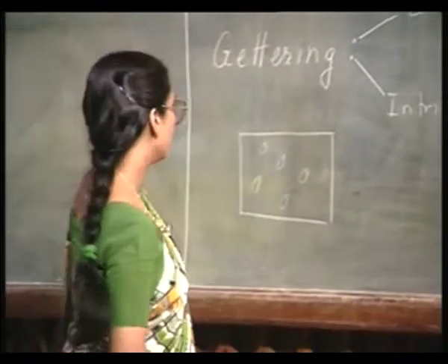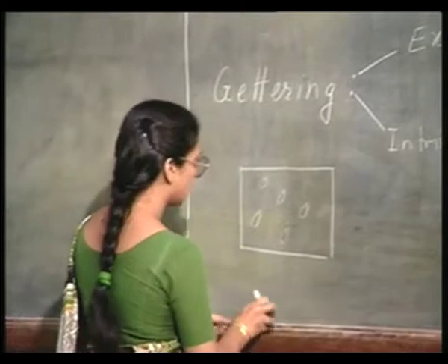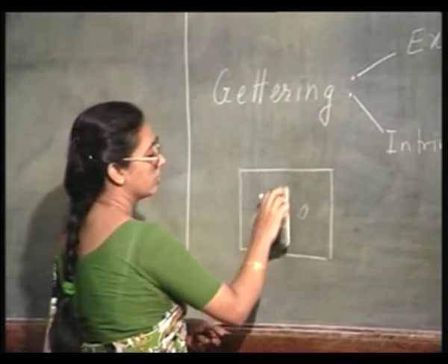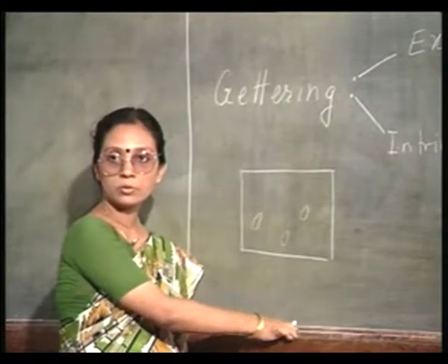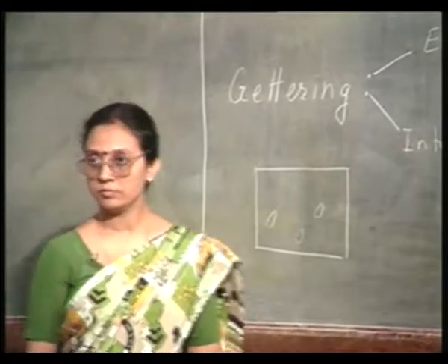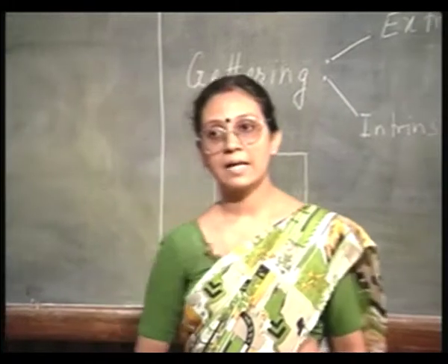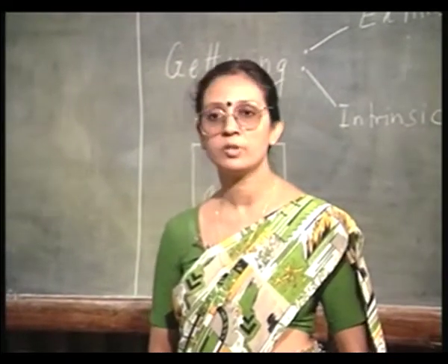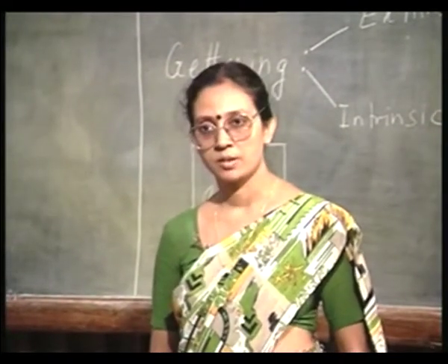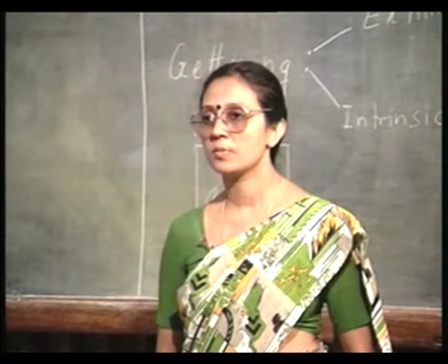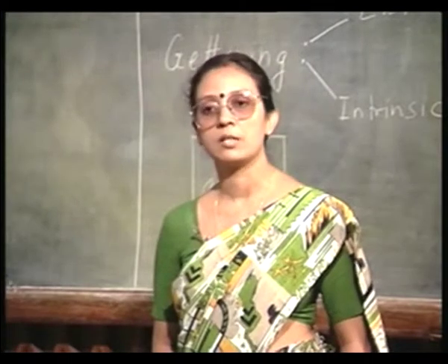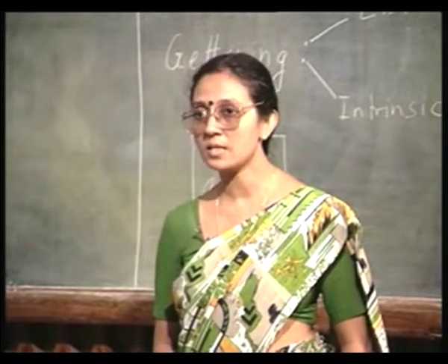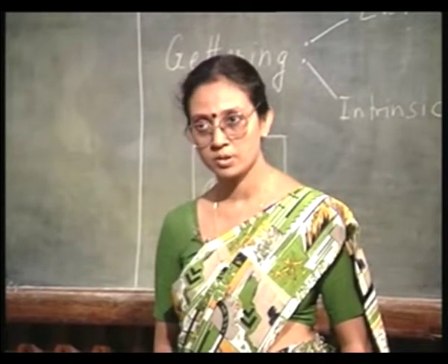The oxygen from near the surface will evaporate out. So, the active region is free of these oxygen precipitates, but I still have oxygen precipitates deeper in the bulk, which can be used as gettering centers, as sinks for metallic impurities.